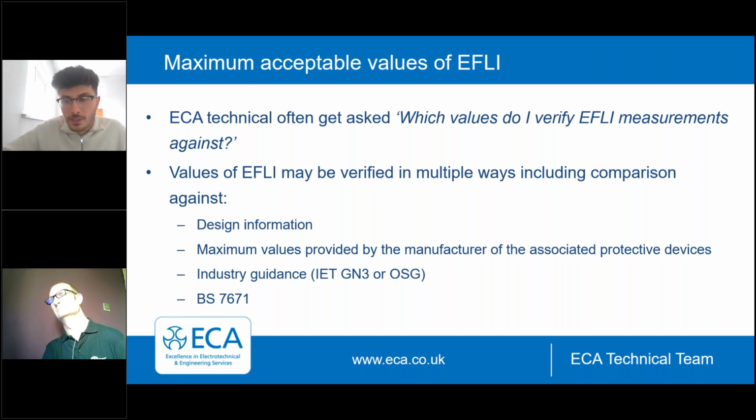And on top of that, the other question, which I'm going to look at here as well, is which one goes on to the schedule of circuit details? So which are the maximum values that you should list on the schedule of circuit details, your maximum Zs values? Now, sticking with the initial question, which values do I verify Earth Fault Loop impedance measurements against?